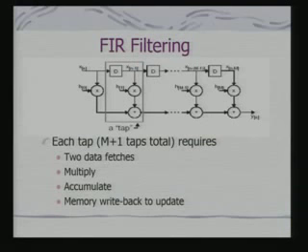operation which is done. Now, if these are the common algorithms, then the basic question that comes up is that DSPs, that is digital signal processors, must have dedicated hardware to facilitate implementation of these common algorithms. We shall look at the simplest of them, and with respect to that try to understand the requirements of the architecture and see how that is really realized in different digital signal processors. So the simplest one is FIR filtering.